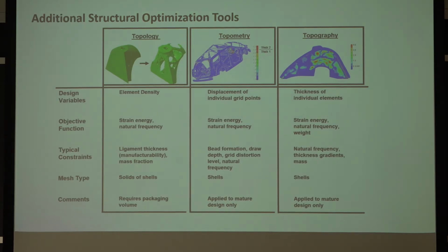Okay, so you can have 600 body panels or 700 body panels, and then you can assign a thickness to each of those, and then that becomes the design variable. Given certain boundary and loading conditions, the optimizer will then go through and choose the optimum thicknesses for every panel to give you the lightest structure.